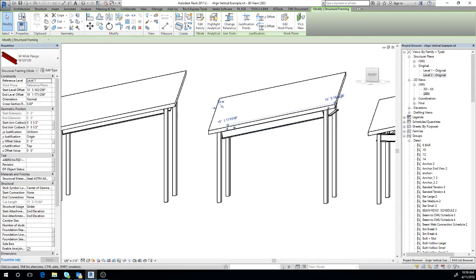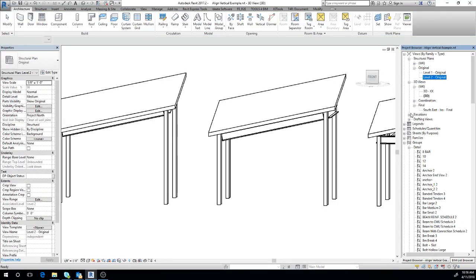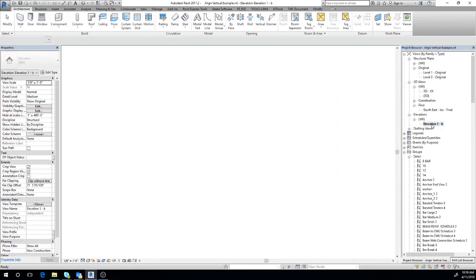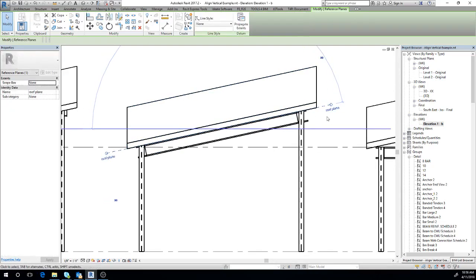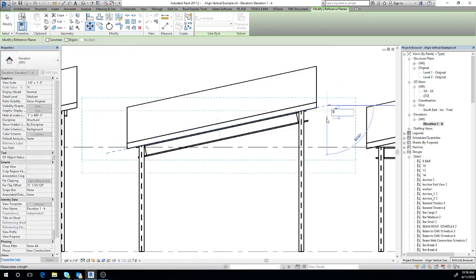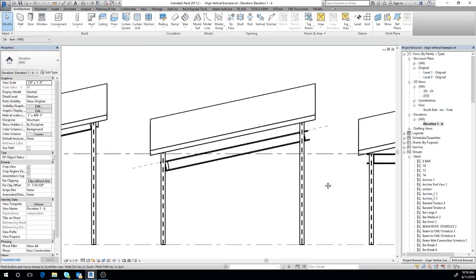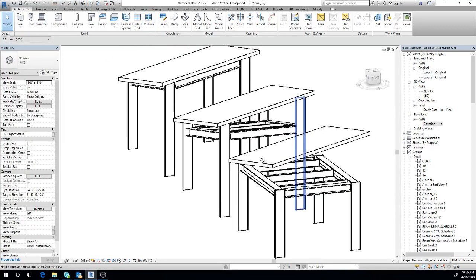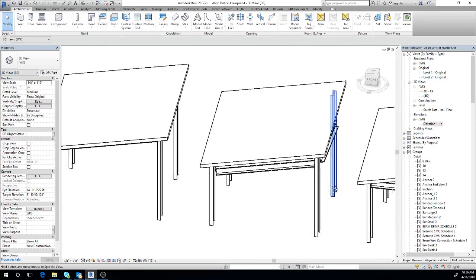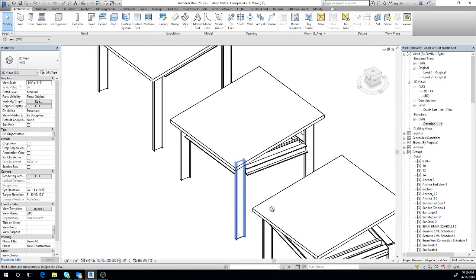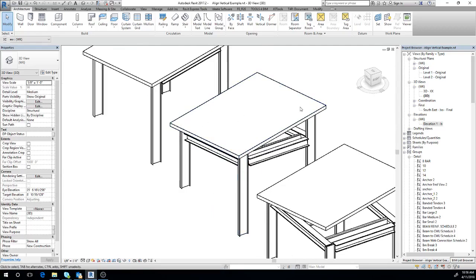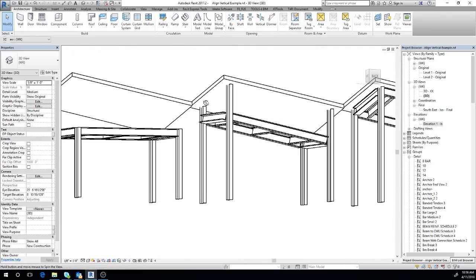The advantage of this is that if we go back to our elevation and change this, say they tried to move it down 1 foot, everything on that plane will be affected as such. So, back to 3D. However, as we were pointing out before, we can't actually do 2 directions unless we figure out the exact slope and then have a cut through there to draw our reference plane, because it can only be perpendicular to the camera, which is, yes, rather frustrating.